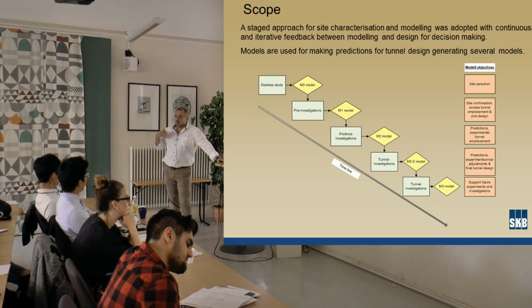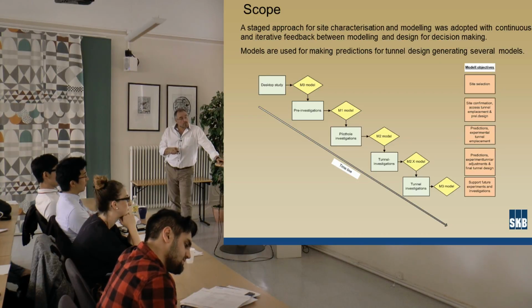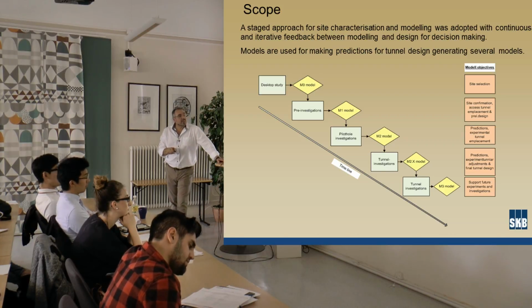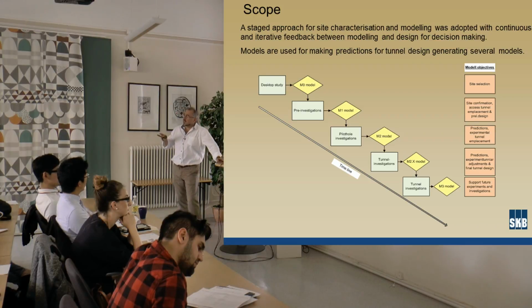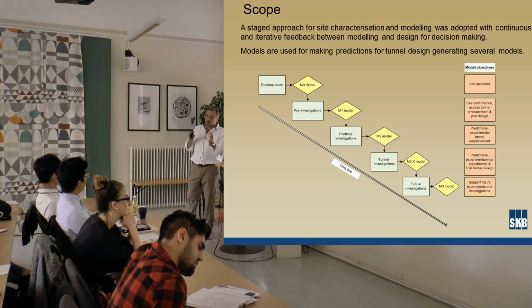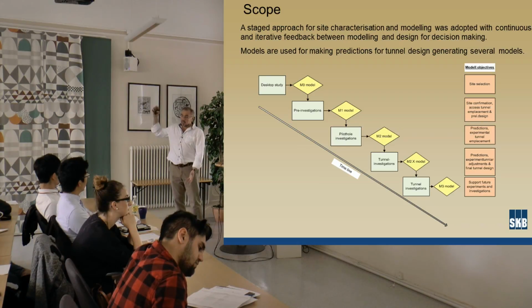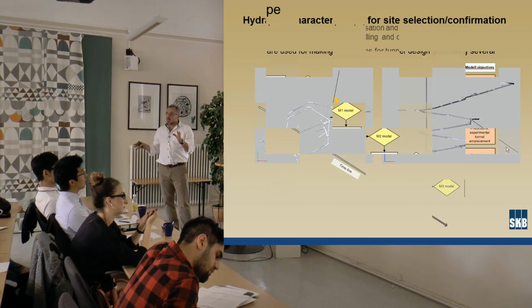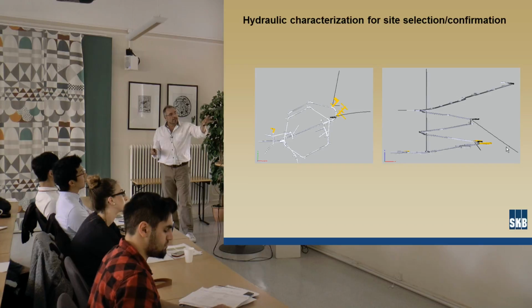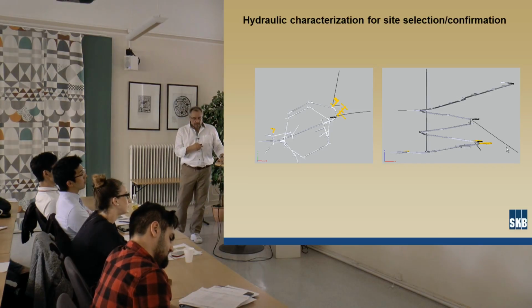and during tunnel construction there were several investigations undertaken. And then, during tunnel construction, we produced several sub-models, 2.x. The objective with this model 2.x was predictions, experimental tunnels, and to adjust and fine-tune the actual layout. How should we place the tunnels? Which one should be grouted? Which one should not be grouted? Where is the high pressure which they want? And so on. So these are the two first holes. After we made the model M0, the two pre-investigation holes were drilled.